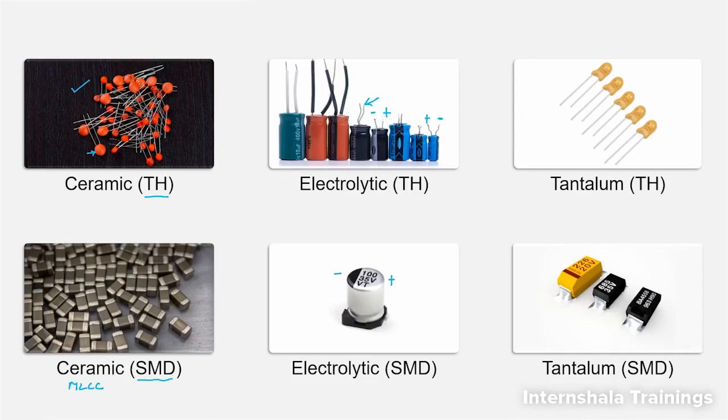Okay, electrolytic capacitor. And in case of ceramic capacitor, there is no polarity. So you can connect this ceramic capacitor in any direction, whereas in case of electrolytic capacitor, you have to maintain the polarity. Okay, if you connect the electrolytic capacitor in the opposite direction, then you may damage the capacitor or it may also blast. So always remember that point. So these were the electrolytic through-hole and SMD capacitors.